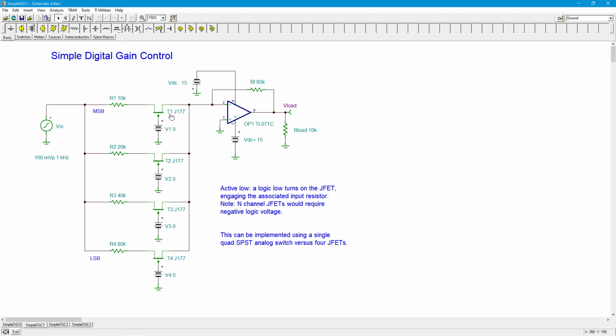So this one is set up so that a 0 to 5 volt signal will do the appropriate switching that I want. So if I have 5 volts out of here, this FET will be in the off state. So it's basically an open switch. Okay? End result, this is not being affected. The signal is not creating the appropriate input current going through the summing node.